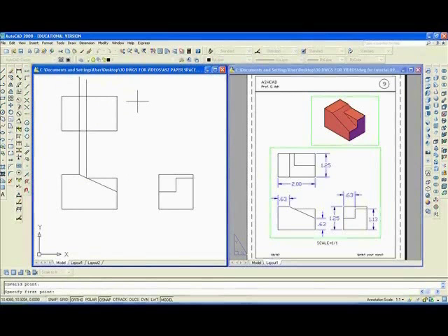and we'll offset 0.63, escape. Undo that, it was a mistake. Going to offset 6.3. Okay. Escape, F enter, fillet. We'll clean up that intersection. Then we want to trim, TR enter, from that line and that, enter.